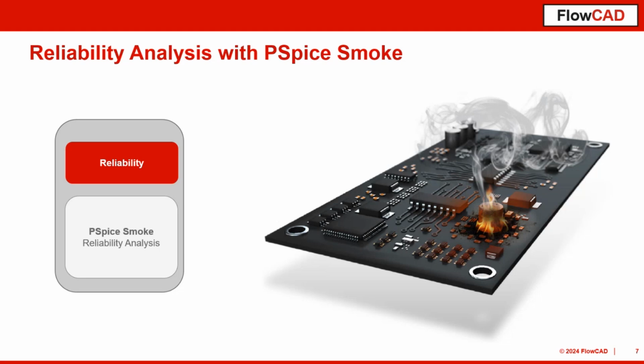The stress can be caused by power dissipation, or by an increased junction temperature, for example. Components have voltage and current limits. Semiconductor devices have other kinds of limitations like breakdown or secondary breakdown limits. All these kinds of limits are respected by Smoke when the parameters are set.